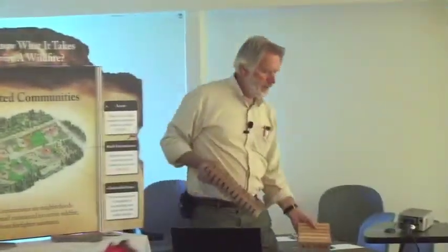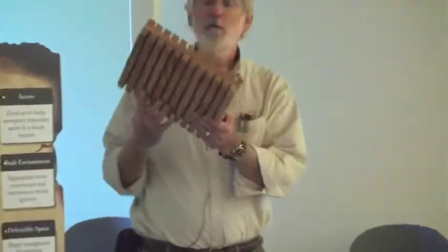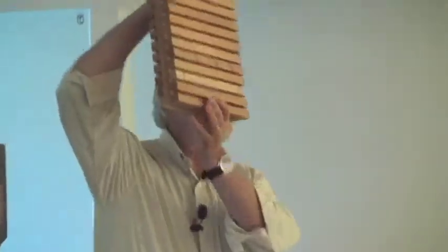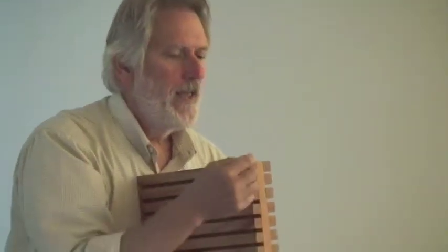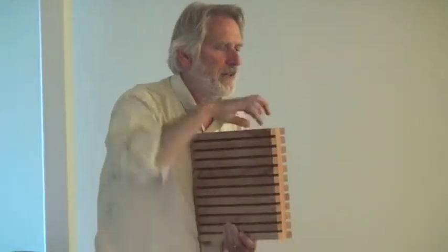The one that we're looking at here is the brand test. And what we see in this particular test is this Class A brand. It's a 12 inch by 12 inch piece of material, and as you can see, it is a sandwich construction. It's 3/4 inch square Douglas fir sticks that are nailed together. The middle layer of the sandwich is perpendicular to the outer layers, so you have a lot of holes in it.